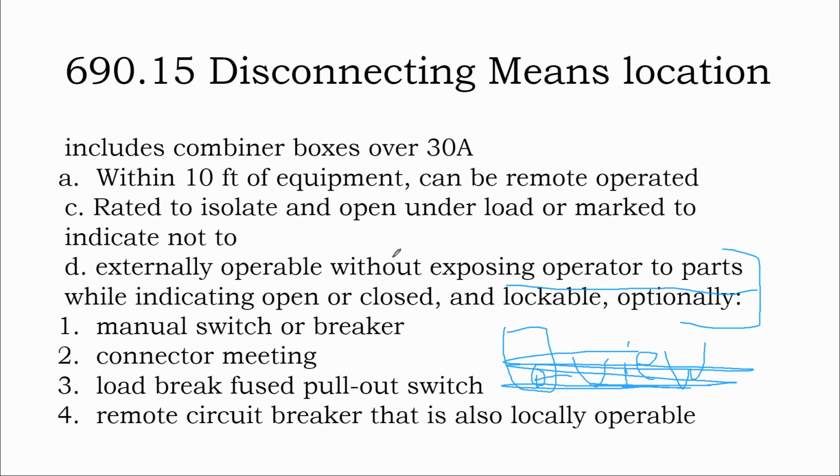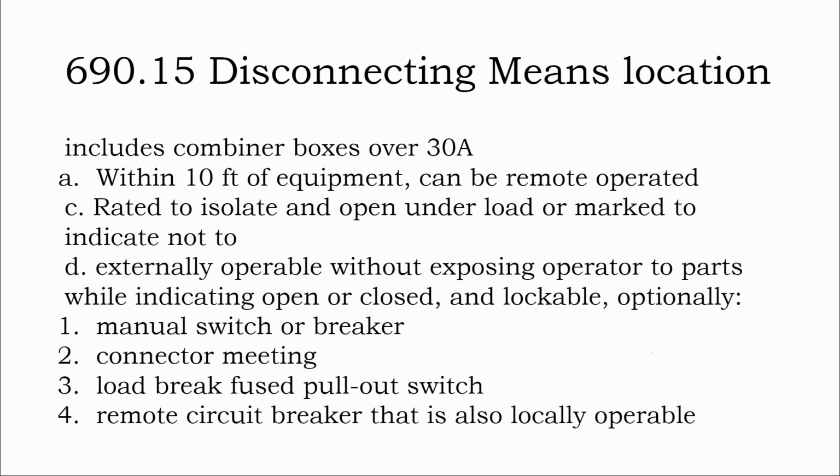It's just a very common one. When I'm buying a disconnect switch, if you're just doing a simultaneous disconnect of each 120 volt pole, it's probably cheapest just to buy a 2-pole non-fused disconnect switch.